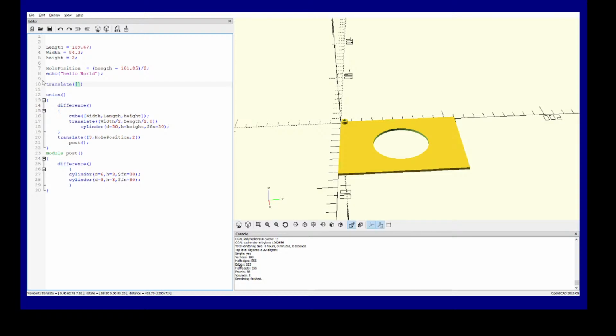So the next thing we can do, if this doesn't work, is we can say translate, and we'll do something spatially. So I'm going to say this line again. This is another way to figure out where it is. The hole position, I'm going to copy this line. I'm then going to say that it's 5 above. We'll do a cylinder that's 3. So I'll copy this. This is just so I can see if something's spatially centered. And we'll call that 2. We'll see what it looks like.